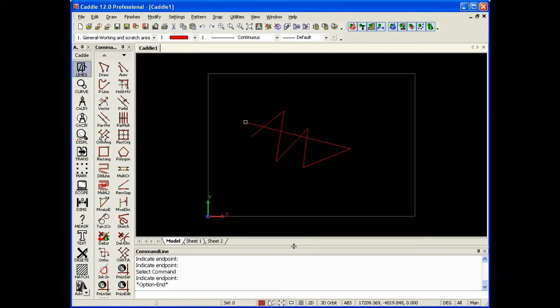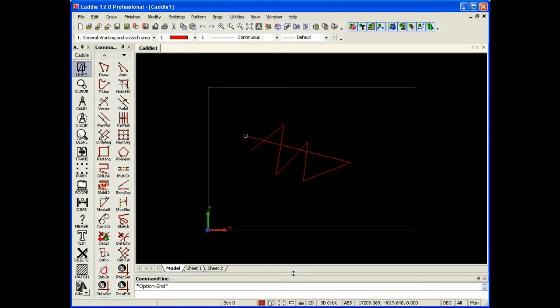With our slightly atypical space, although I suppose you could use this on things like laptops and notebook computers, we might want to maximize the space that we have available for drawing. And we see that we can grab things like the command line and just bring it down to give us more drawing area. We can still toggle through line by line, going through the prompts that we've had on the command line, just using the arrow keys there.